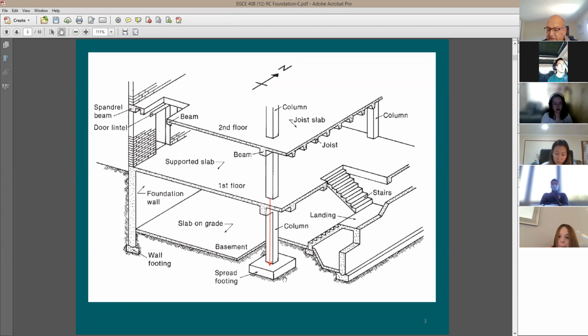So we have two main issues when it comes to designing a foundation or footings. Number one is going to be the size of the footing in terms of length and width. In terms of length and width, now you start to think which one here is stronger. Is it the soil or the concrete? And of course, it's going to be the concrete. So we have an issue with the soil, that we want to be sure that the soil allowable bearing pressure is still okay.